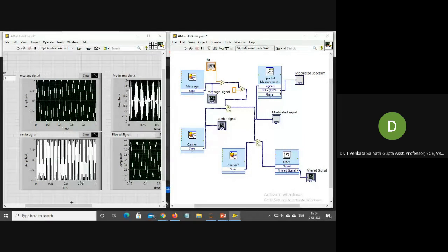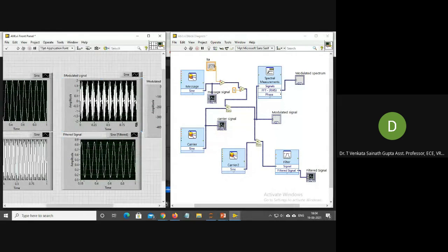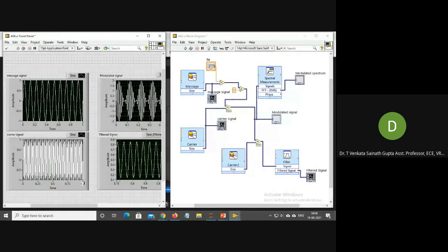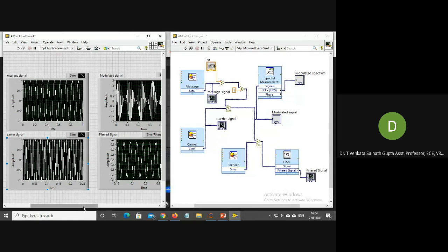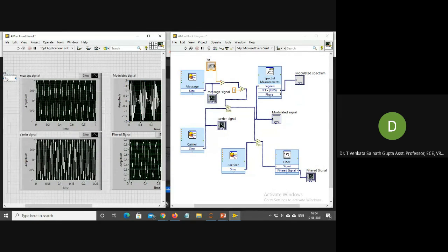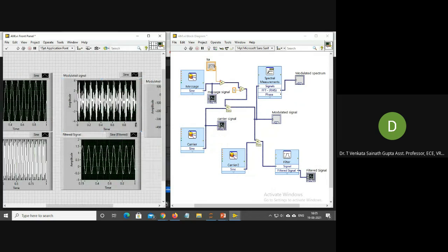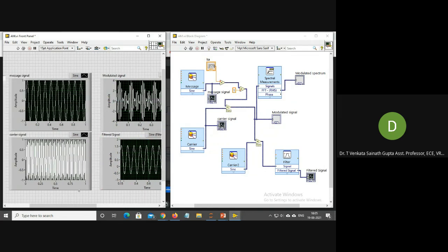You run this. Again, you can adjust this. So this is critically modulated signal, and this is the carrier. Similarly, you can do this for over modulated signal. You double click on this one. You can see that there is a crossover happening. There is some minor lobe type of thing that is appearing whenever I am giving this Ka as greater than 1. And this is your carrier.